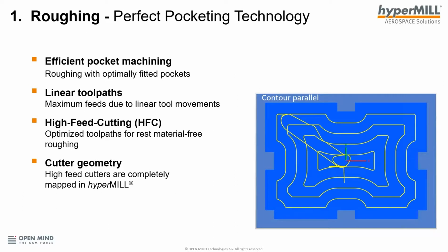You make a number of step over passes, and then you link these together. With these connection macros and how it connects from one toolpath to the other, this is not so great for hard materials because it puts forces into these areas where it's not as stable as it could be.